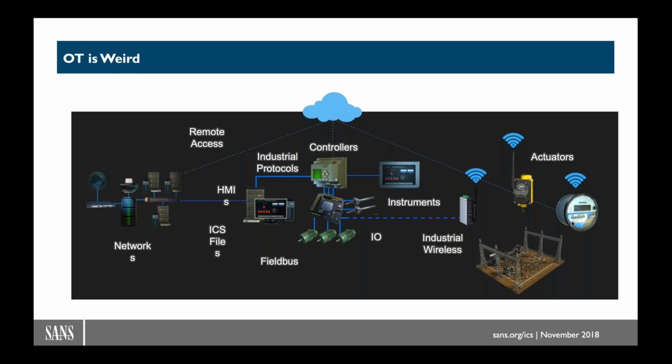You certainly have those devices, and you have traditional host logs, network logs, traffic to do some analysis of, but you also have some additional things that are high priority, like process alarms or operational alarms, various device logs from a wide variety of different types of industrial control system devices, plus the configuration file analysis within those devices, operational sequence of event data that may be important in trying to identify some type of an event of interest, a variety of different communications analysis components, and a number of other secondary systems that could be important in identifying events of interest or events that need some additional incident response.